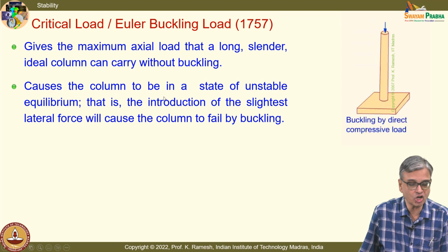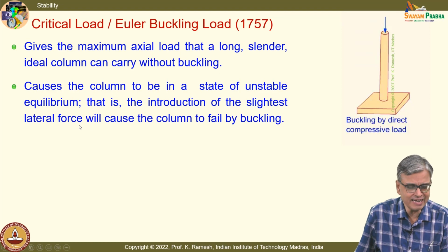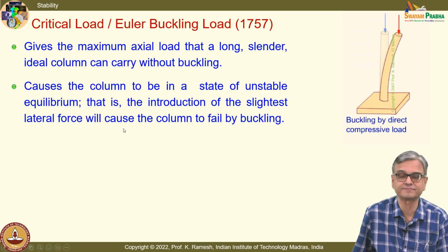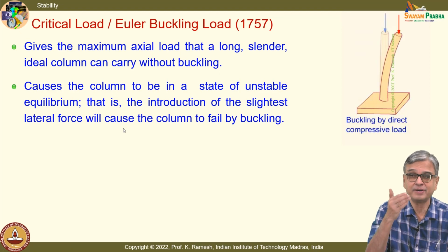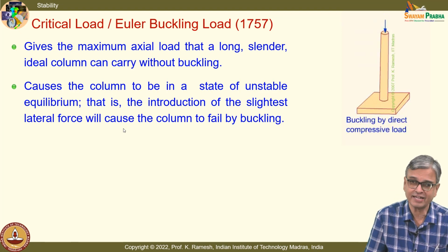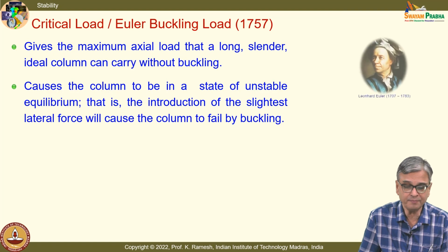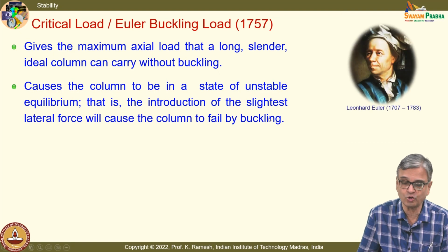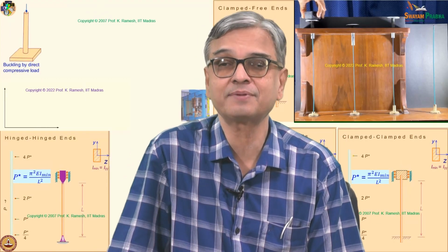So, you have to appreciate what causes the column to be in a state of unstable equilibrium. Introduction of the slightest lateral force will cause it. That can be inherent in the material itself. Okay, there could be material defects, or there could be problems because of the loading. And column buckling, the credit goes to Euler, and he was a great mathematician.